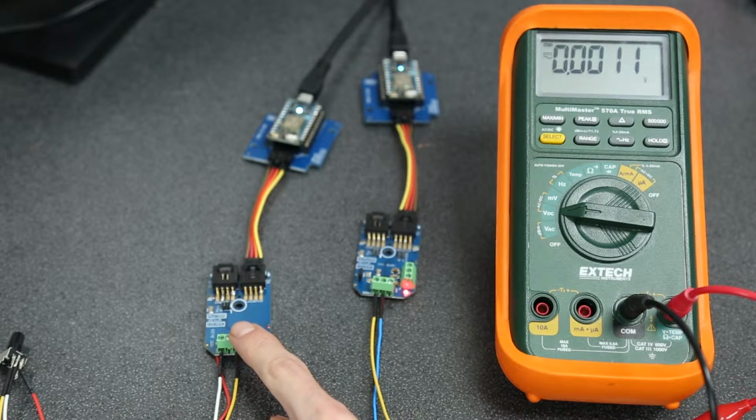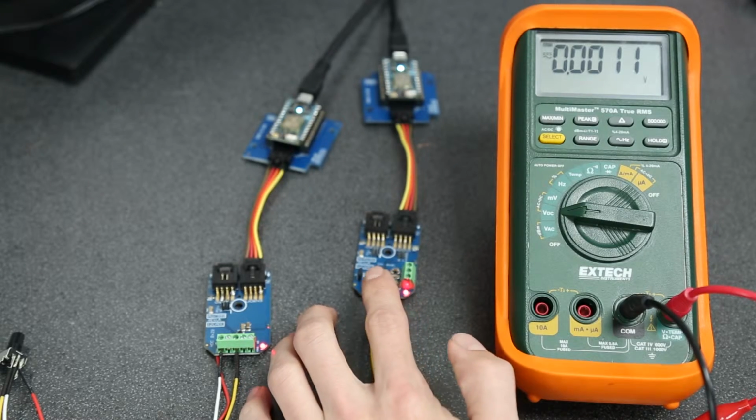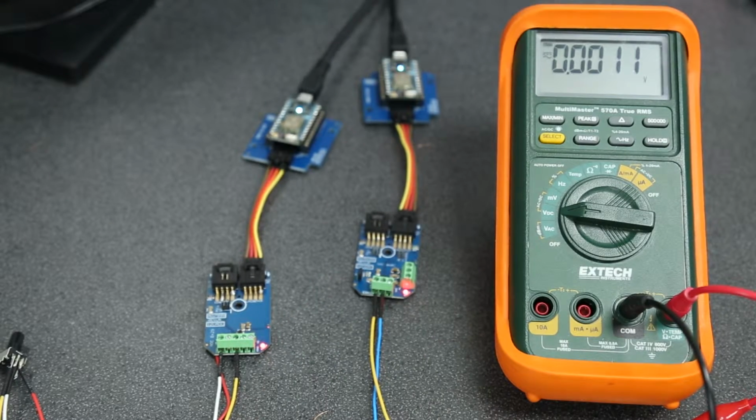This ADC input board could be used for reading 0 to 5 volt DC signals or variable resistance or digital contact closure signals. The DAC on the other end is going to provide close to a 0 to 5 volt DC output. The maximum output of this module is based on the supply voltage to the chip.